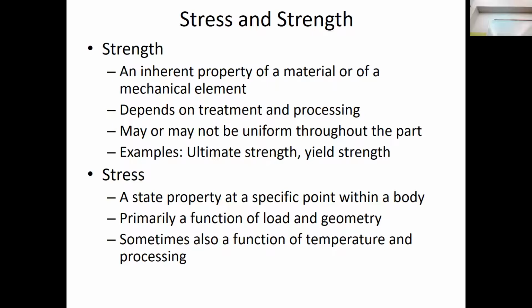And with that being said on an area, I can tell you that the internal force is a resultant of the stresses applied on that section. So the stress is applied at a point. When you find the resultant of all these stresses, you get to the internal force. So if we integrate the stress over the cross-sectional area, we get the internal force.